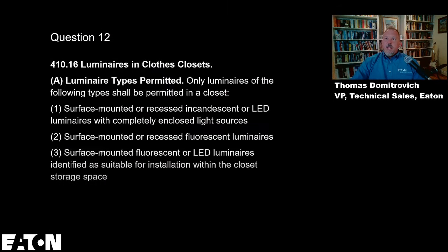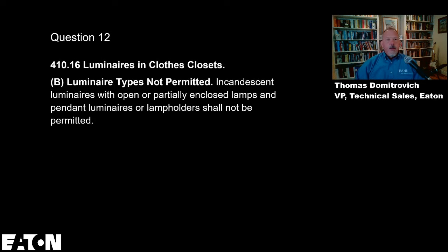All right, so I'm going to continue with question 12. Luminaire types permitted, and we already talked about this. Only luminaires of the following type shall be permitted in a closet, and they talk about the recessed incandescent, and they talk about the LEDs. Surface-mounted or recessed LED luminaires, surface-mounted or recessed fluorescent luminaires. So they pulled that incandescent bulb out of there. Not permitted: incandescent luminaires with open or partially enclosed lamps, and pendant luminaires or lampholders shall not be permitted.